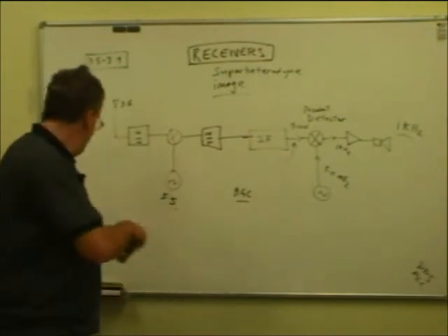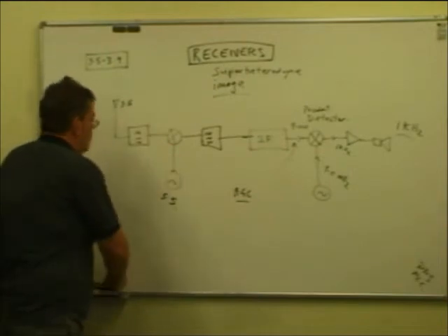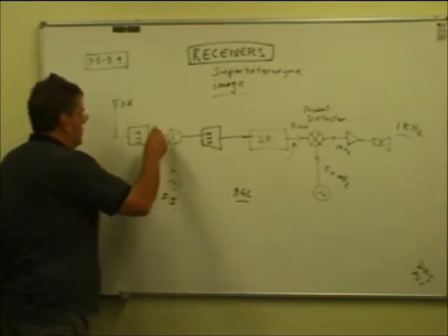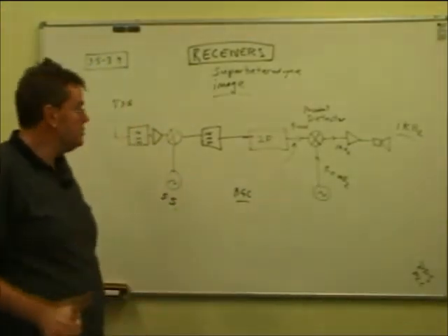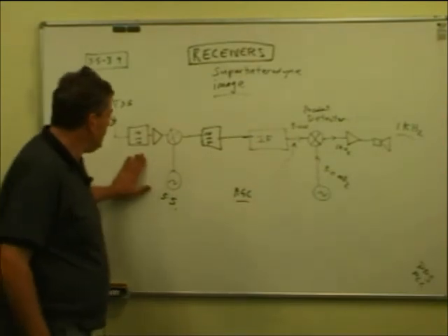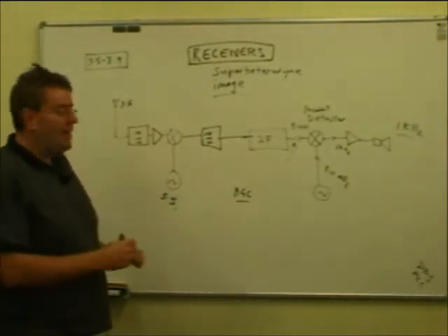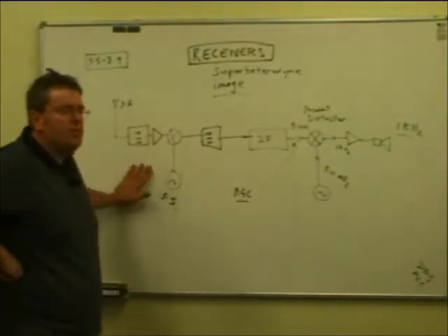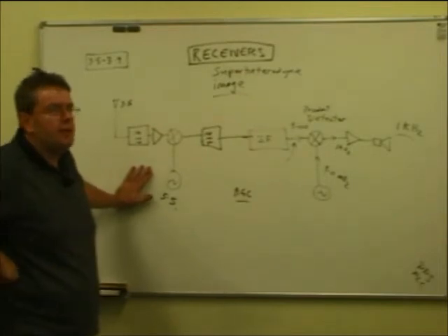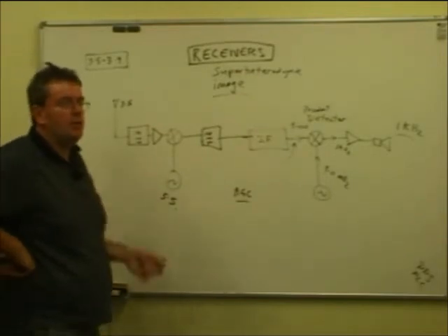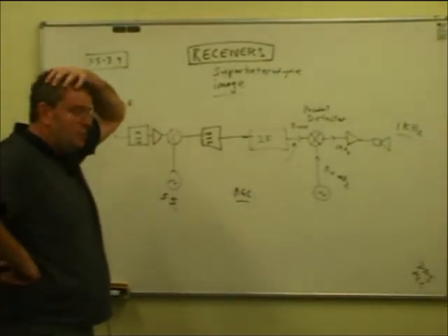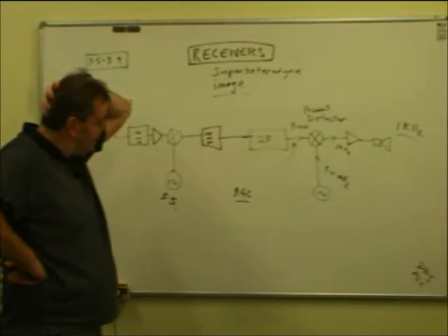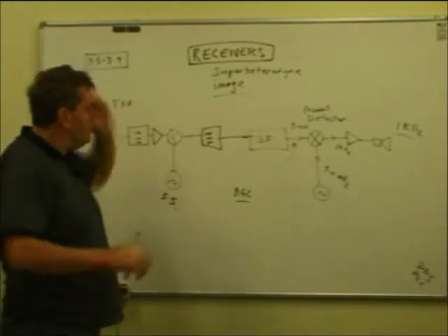so there's no point in making the receiver that sensitive. And the RF amplifier, which I left off, will often be switched out on the lower bands because it's not required, and it can degrade receiver performance in other ways, which we might mention towards the finish. On the higher bands, it's certainly useful to have it there. But the strongest signals might be many millivolts. If you've got a ham just a few hundred metres, a kilometre away like I do, his signals are incredibly strong. So the problem you have is if you want to tune from one to the other, you'll be forever adjusting your volume, your AF gain.